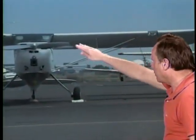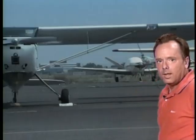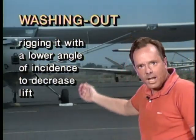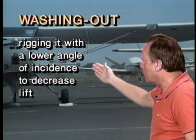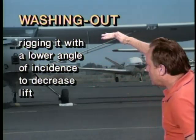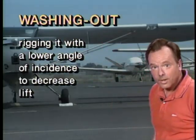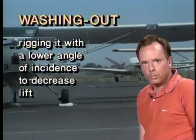about the angle of incidence of the wing all the way from the root to the wing tip. And washing out of a wing is done by rigging it with a lower angle of incidence to decrease lift. So if you change the angle of incidence of this wing so that you lower the angle of incidence to decrease lift, that's called washing out of the wing.